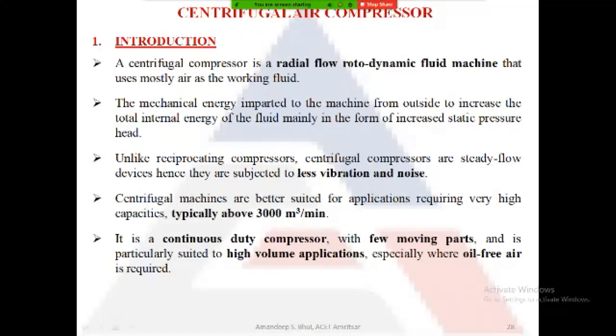Fluid machine: in this we are using air, and air is a fluid, so hence it is a fluid machine. So the proper terminology to define a centrifugal compressor is radial flow rotodynamic fluid machine. Okay. So this can be another name for a centrifugal compressor.